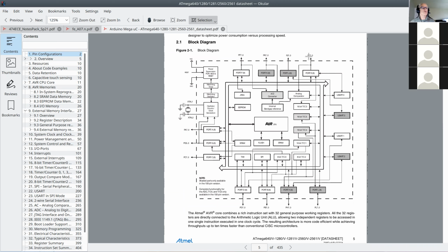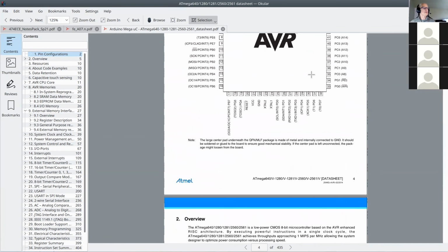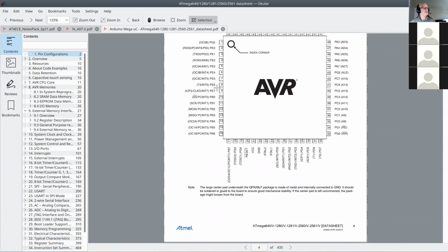So port E, pins 0 through 7 are the 8 bits of port E. And then if you look up here, well, E6 is pin 8, and that's the chip's pin. And then Arduino has yet another pin number. So we're going to learn how to trace the pin numbers all the way out to the external connector here that is easy for us to connect to.